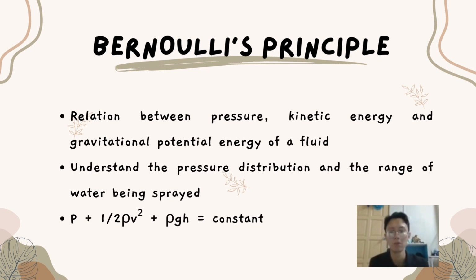So according to Bernoulli's principle, a decrease in the diameter of the pipe causes an increase in the velocity of the fluid, and it brings a decrease in the internal pressure in the pipe. So water flowing through a narrow pipe will create a high velocity spray, meaning it accelerates when it exits the nozzles, and hence plants at a longer distance can also be watered by the auto water sprinkler.